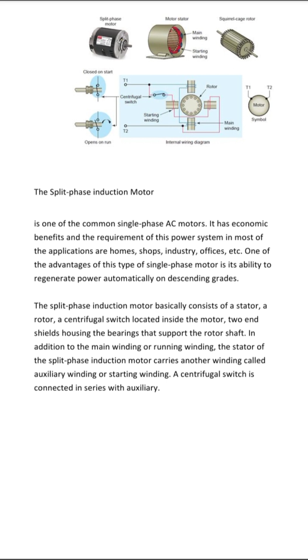A phase shift to the main current is achieved by using narrow conductors to achieve a high resistance to reactance ratio. Increasing the resistance means that the auxiliary winding can only be used during starting, otherwise it would overheat. A split-phase motor has significantly lower starting torque due to the reduced phase angle between main and auxiliary winding currents. The application of this motor includes different loads which are used for general purpose due to excellent starting torque and easy direction reversal characteristic.